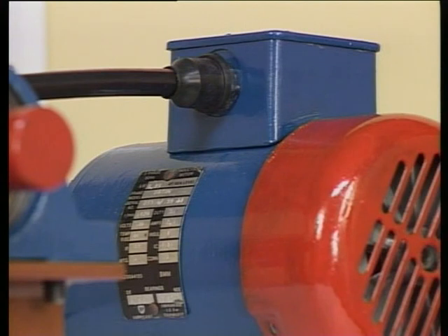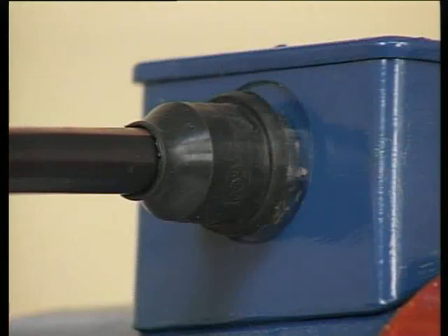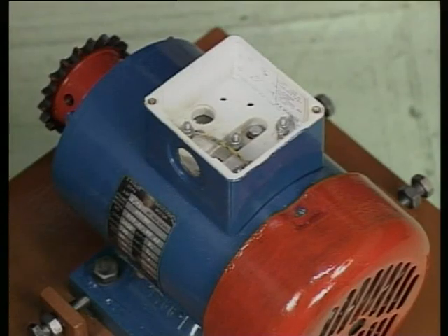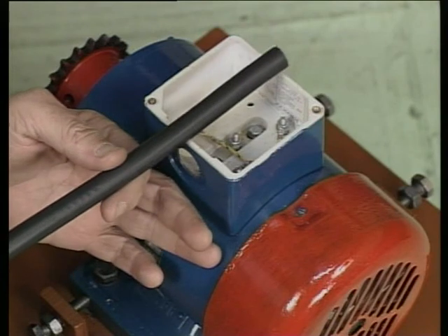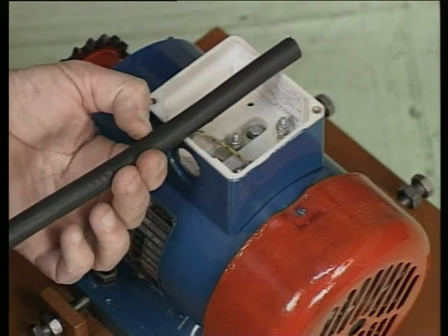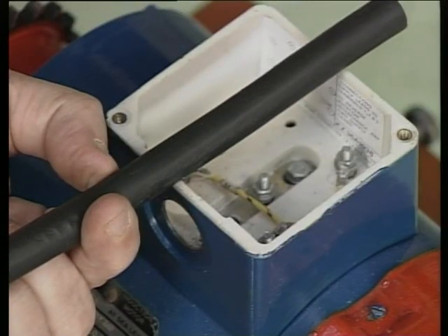In virtually all industrial applications, a cable is secured, at the installation, by a cable gland situated at the point of cable entry. For purposes of explanation of principles, we have selected a 4-core armored cable for the supply to our motor. The cable must first be approximated into position at the furthermost terminal, and the point of entry be marked as the starting point for cable stripping.